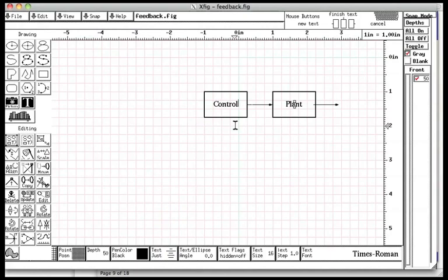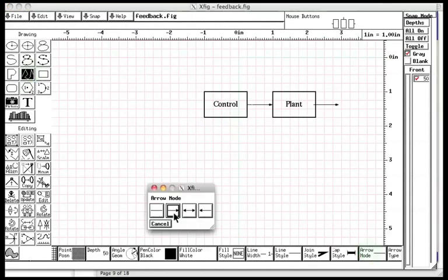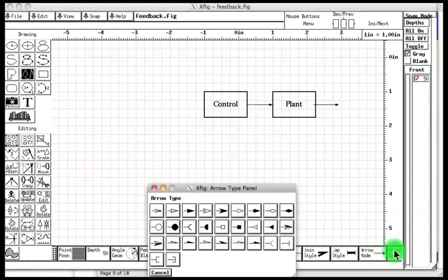and click the mouse. We would now want to enter some more lines with arrows. Let us choose the Polylines button. Let us select the Arrow Mode button from the Attributes panel and select the second option. Let us click the Arrow Type button and an arrowhead.